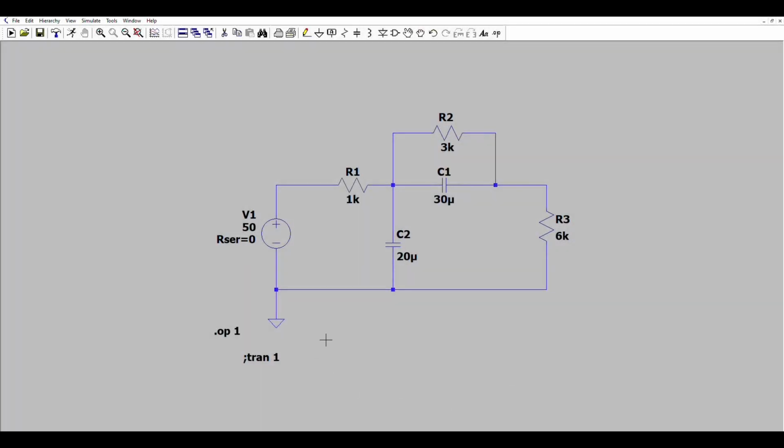I want to simulate the last example that we've just solved, example 5, using a CAD tool, using LTSpice. Let's take a look at it. This is example 5, drawn using LTSpice. This is V1, this is V2, this is V3. Once we click on this node, we have 50. This node, we have 45. And this node, we have 30.